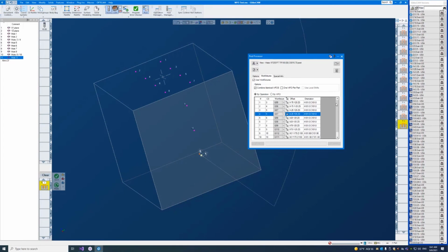Previously, you would have had to have a separate post processor for that. Now you can just check one work fixture per part, and you've immediately dropped into G54 mode. So everything is G54, and you're now doing D style output. So just one checkbox.